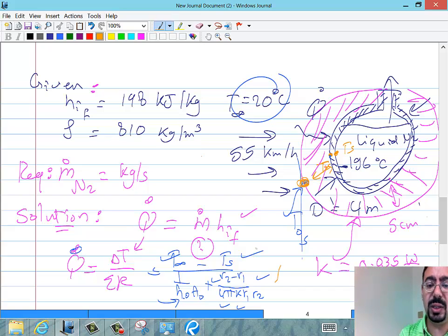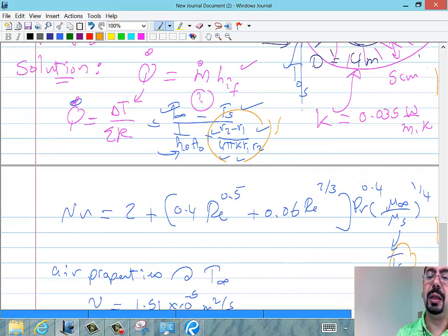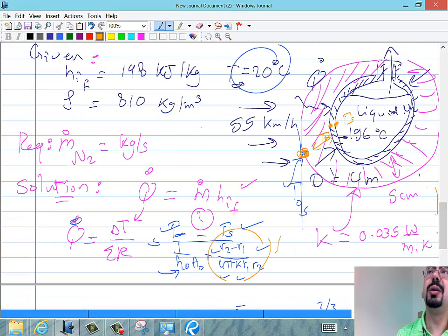Well, the resistance, I know the resistance, right? I have this. So it's off of Q and then use that for the surface temperature. This Q is going to be equal to that. But we don't know the Q. So, Q conduction equals Q convection. Yes, but only if you know the Q convection. But see, the problem now is getting Q convection. Mallory is saying, because we did this problem before, if you say that Q conduction is equal to Q convection, then on the convection side it's T infinity minus this T that you're looking for, and on the conduction side it's this T that you're looking for minus the tank temperature.